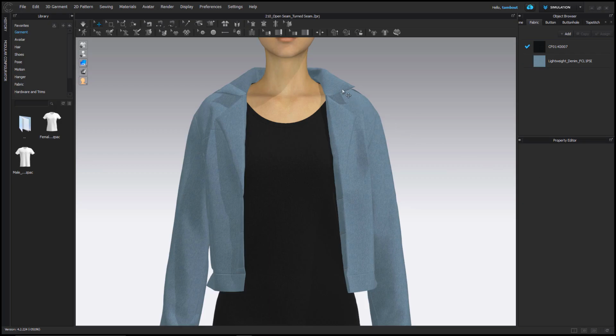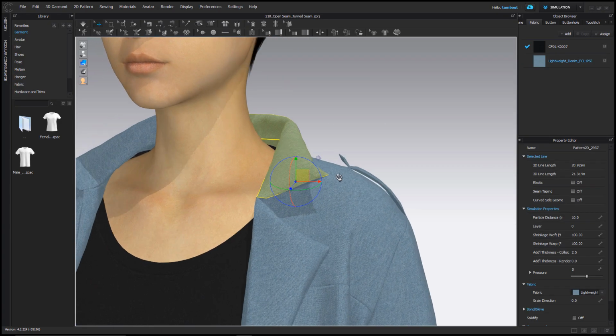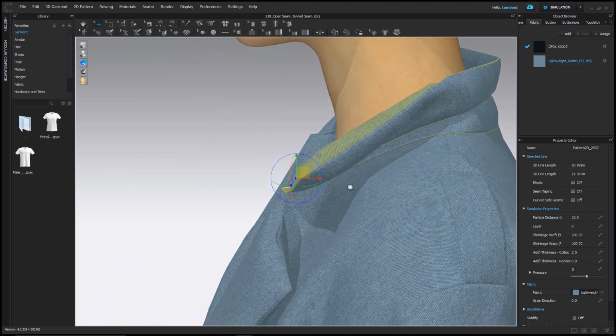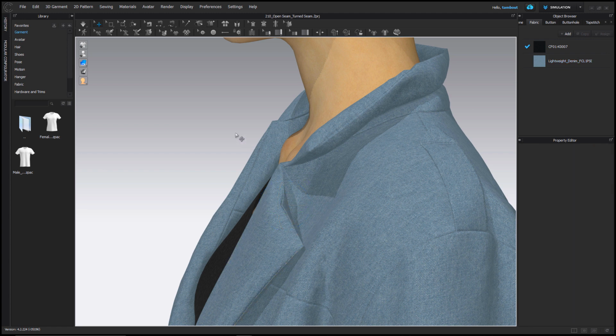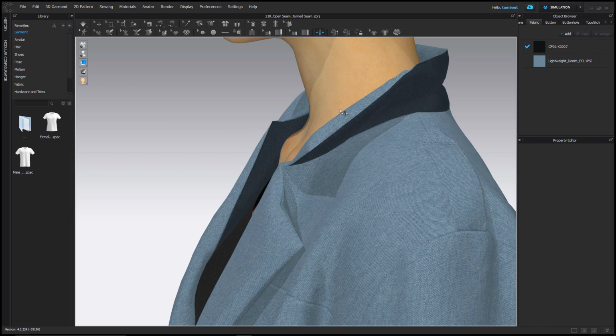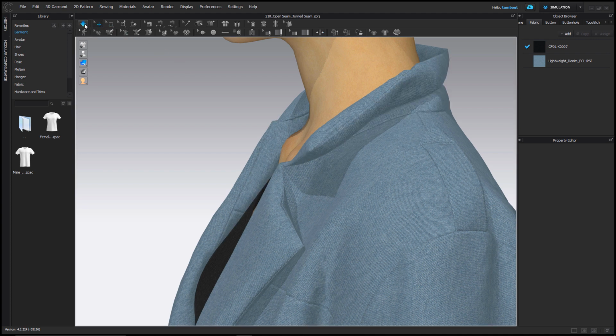Press 3D garments to flatten bulge seam lines when more than 2 layers are sewn together. Notice the rounded seam lines on both the collar and lapel. To smooth out these seams, I'm going to select the Press tool and click on each layer. Simulate to apply changes and watch the seam lines flatten out.